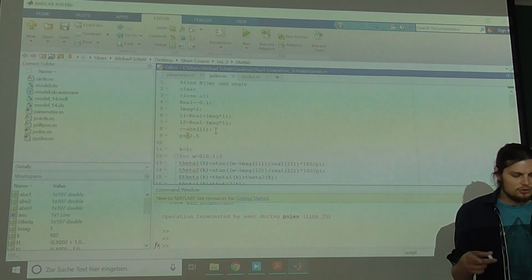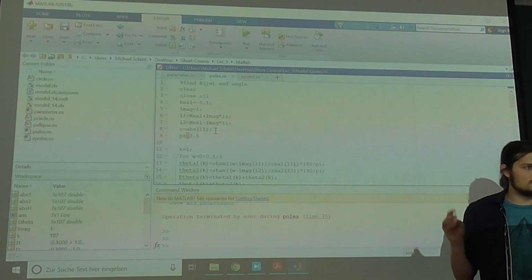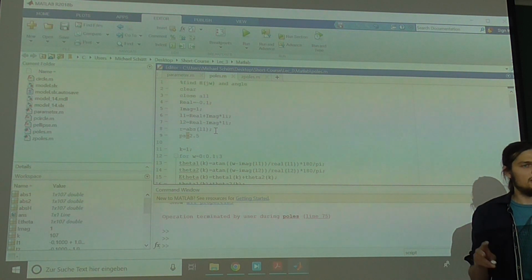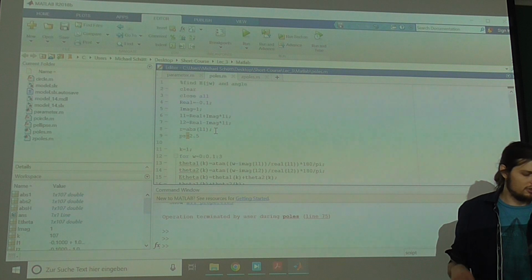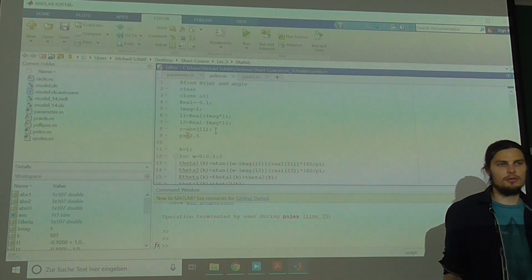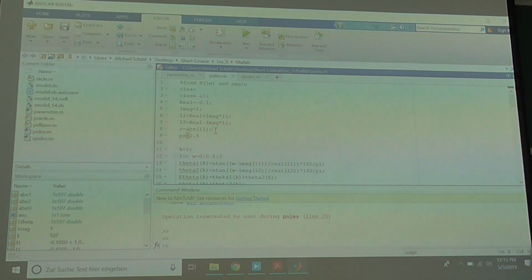And this transfer function, or the sampling relationship between them, changes in different systems. So what people try to do is use approximation models, like maybe you heard of forward Euler or Tustin, very, very often used. They basically say we can approximate this, and we assume that what happens in between is rectangular, or a triangle or something like that. But if it's not really a triangle or not really a perfect line, the integration won't be right.